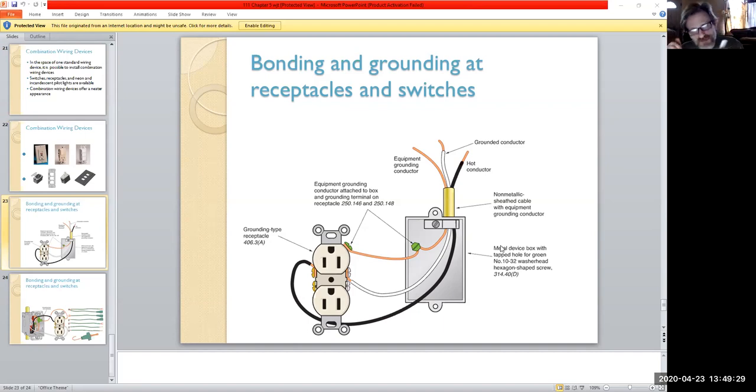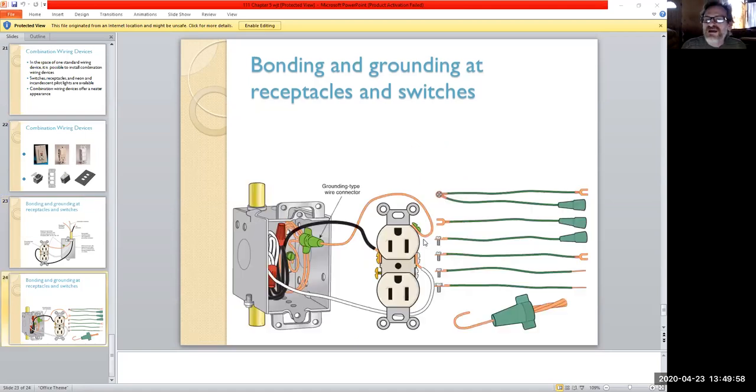And again, remember, 6 inches, 6 inches. Anything over 6 inches, it's 2 wires. Even if it's only 1, it's 2. And that's how, when you have to do size requirements for this stuff, 6 inches is a single wire in a box. Anything over 6 inches in a box is 2 wires. It's just a technicality, but even if it's 7 inches, it still technically would be considered 2 wires at that point, if that makes any sense. But anyway,